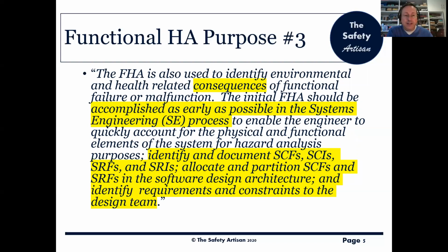And our third slide on purpose. So we use the FHA to identify consequences of malfunction or functional failure, lack of function. As I said just now, we need to do this as early as possible in the systems engineering process to enable us to influence the design. And of course, this is assuming that there is a systems engineering process, and that's not always the case. We'll talk about that at the end as well. And we're going to identify and document these functions and items